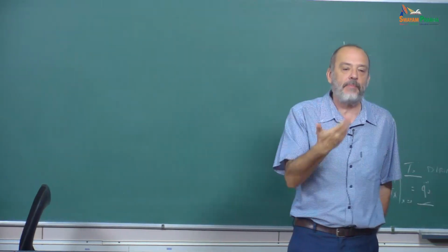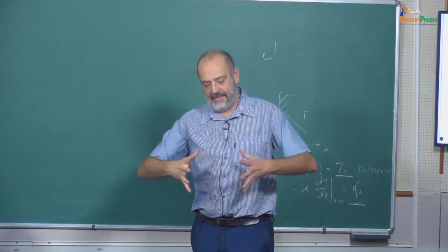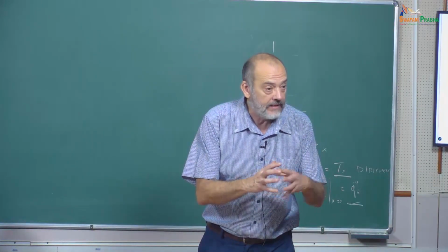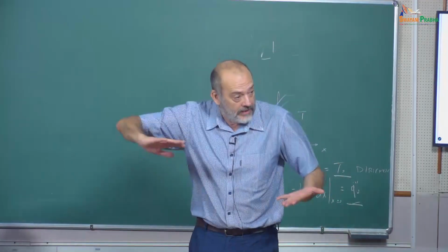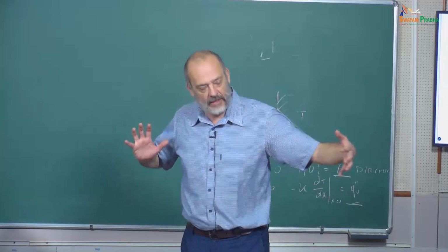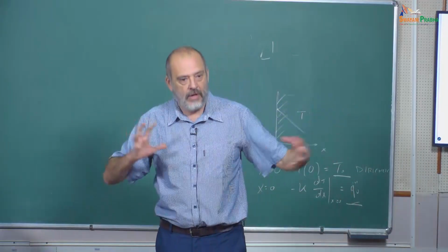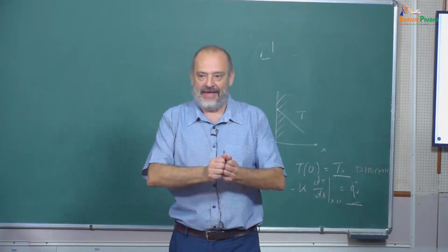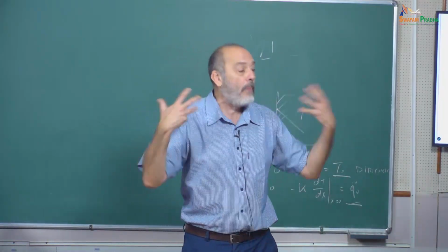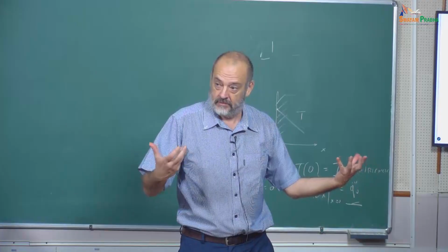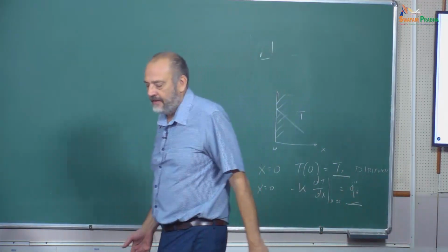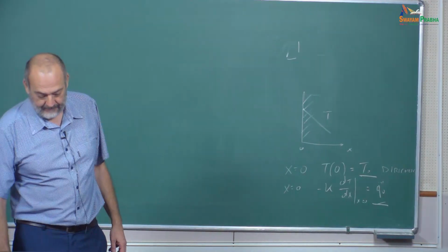So when the fluid is compressible, we think that there is a resistance to compression and dilatation. This is just that. So mu is due to the stresses in this direction. The other one is due to the fact that when we are trying to have an expansion or a compression, there is a force that is opposing this motion. So this is called dilatational viscosity.